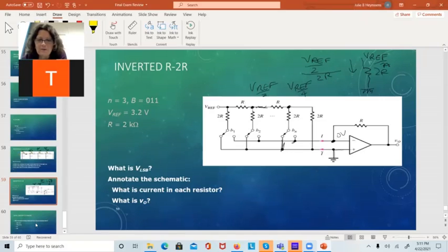Now, if the switch is in a position like here, then the current through that resistor can't go into here. Infinite input resistance, just like a diff amp. All that current has to go through this resistor. And the voltage output is going to be Vout. Since this is 0, got the voltage drop across the resistor. Vout minus 0 is going to equal I through the feedback resistance, that's that little R right there, times R.